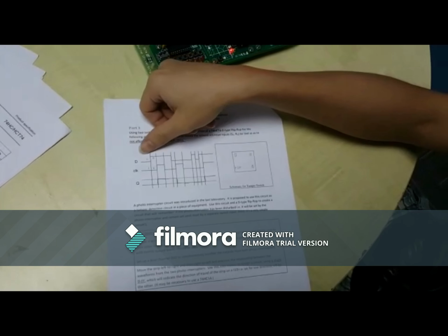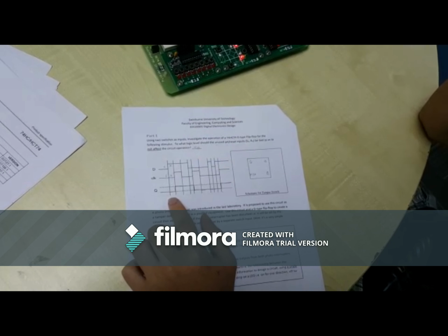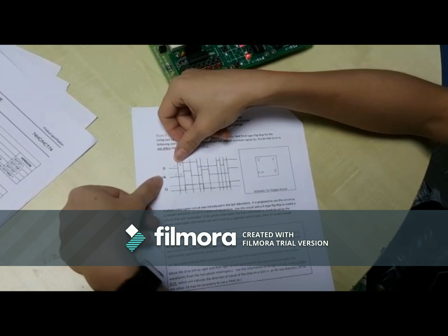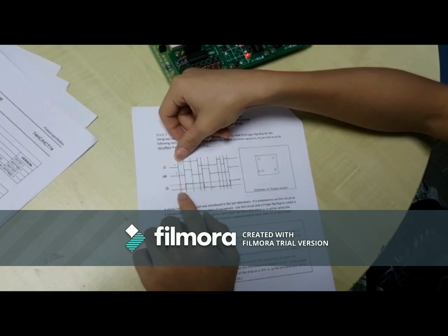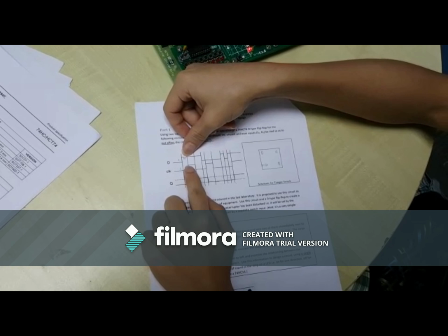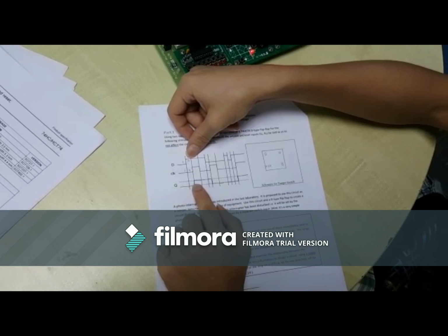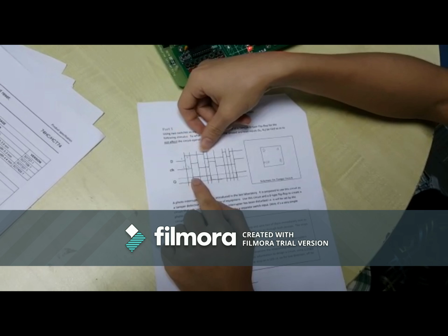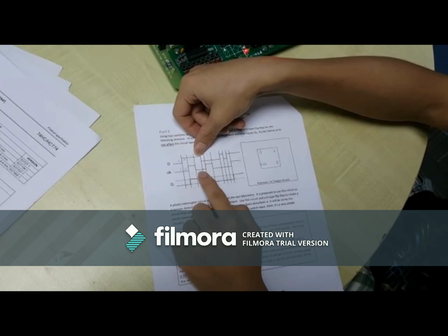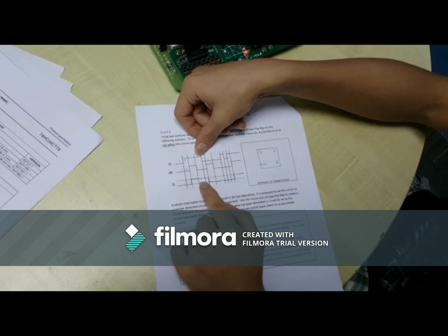This one is the graph that they gave us, and the Q is the output that we have drawn. When the D is high but the clock is low, nothing changes at the Q. When the D is high and the clock goes high, going up, the Q will be affected and it will go up. When the D is 1 and the clock doesn't get high, nothing changes in the Q.